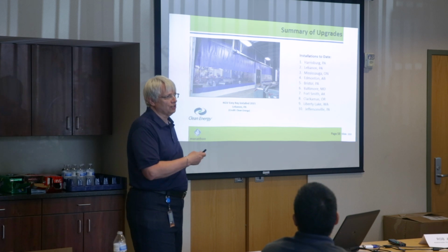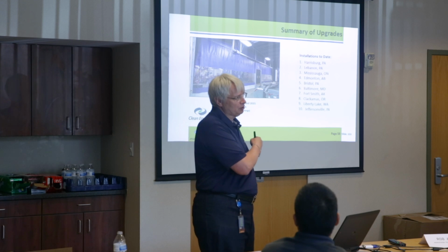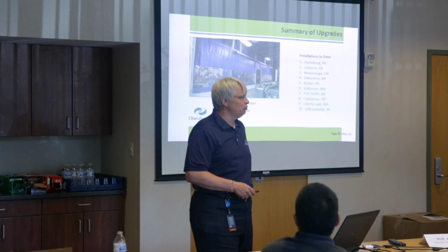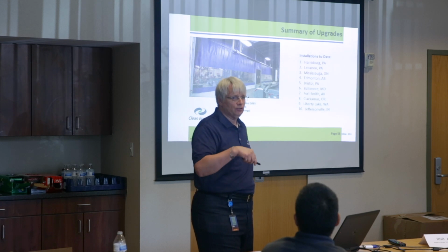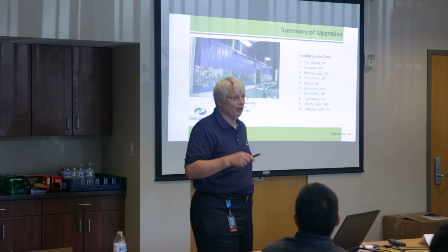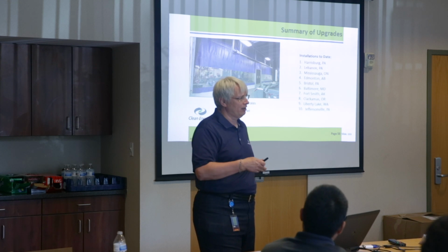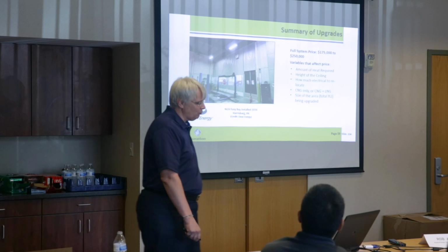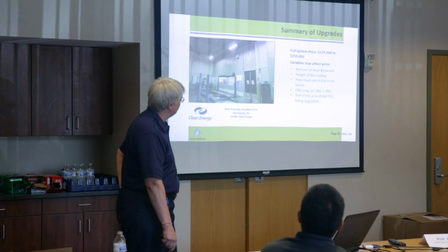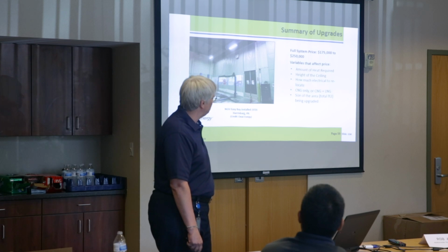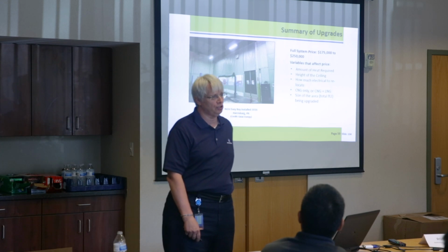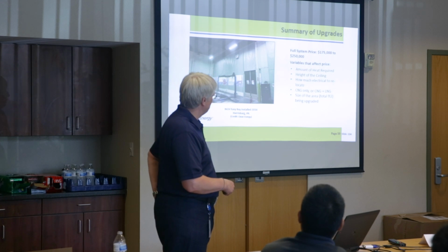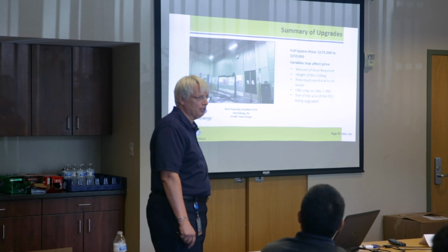So again, the idea here is instead of having to tackle a 20,000 square foot maintenance garage, whatever, you take maybe 2 bays out of that, and you create that little microclimate around those 2 bays and protect that area in the event that you had a release. So I think I have one more picture there. They gave me a full system price of $175,000 to $250,000. These would be applicable for CNG, LNG, or also hydrogen. So although they're primarily in CNG use right now, they would work on any of those 3 applications.